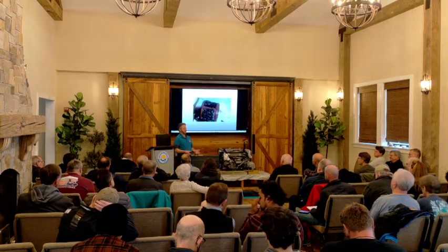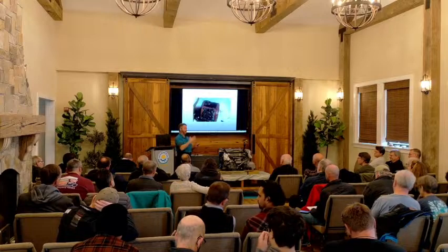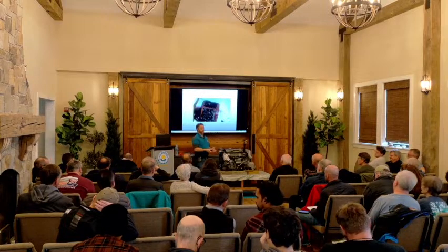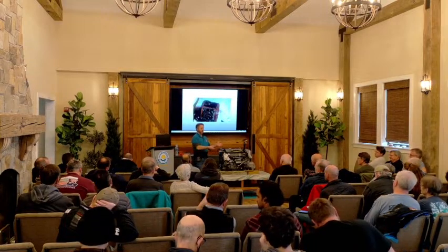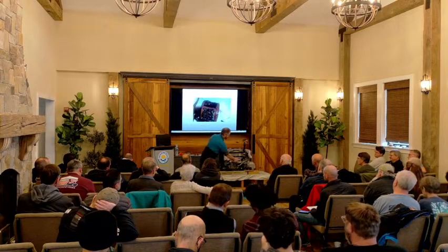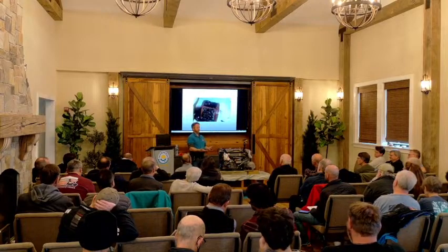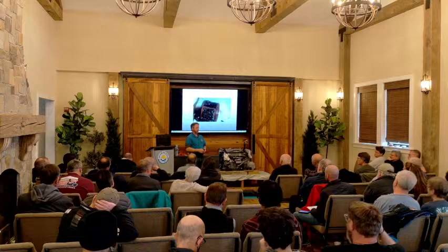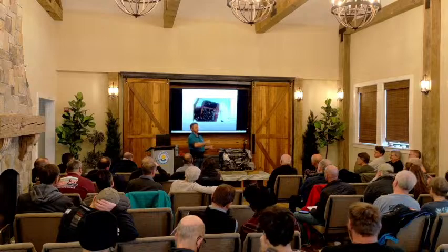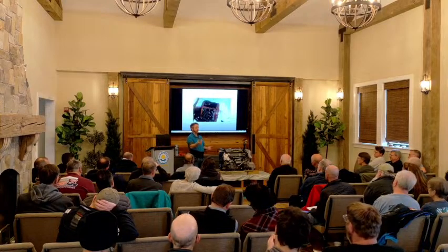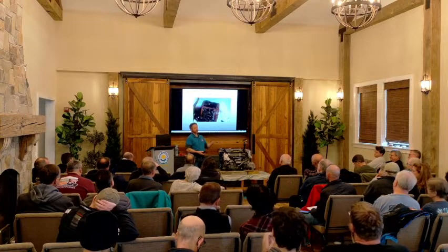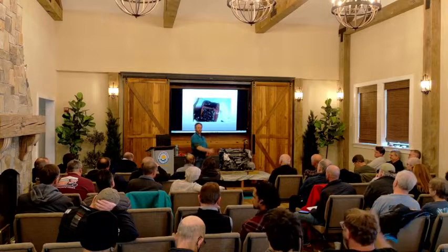The starter's a Hitachi. Trying to find a Hitachi starter is going to be difficult. So you can buy an aftermarket, which is a Chinese knockoff, for like 125 to 200 bucks, or you can buy the Hitachi from Yanmar, which might be like $650 to $700. So what we usually recommend is buy the aftermarket and then send your original Hitachi to a starter shop and get them to rebuild it. That way you have an OEM that's been rebuilt, so if your knockoff only lasts a couple of years, you have a good one to put back on.